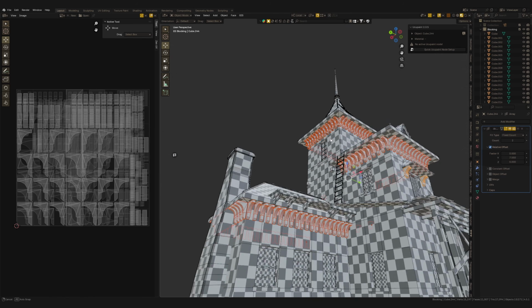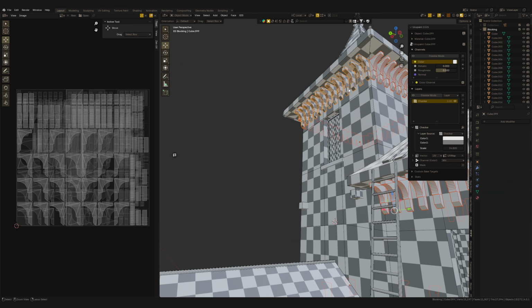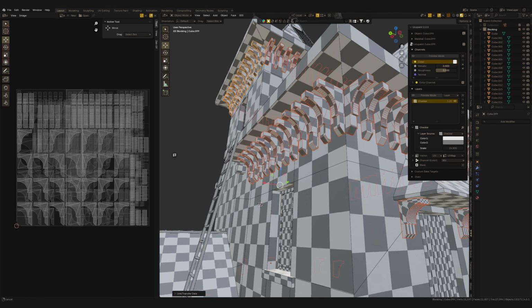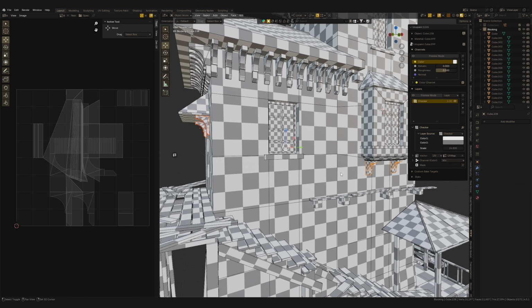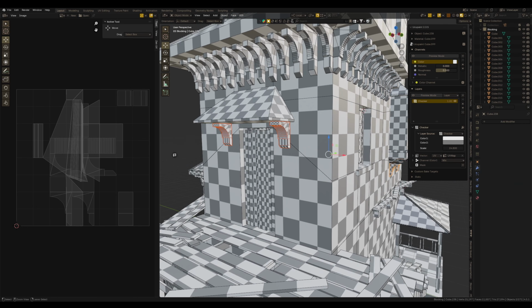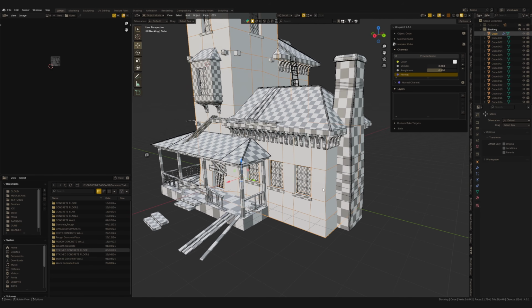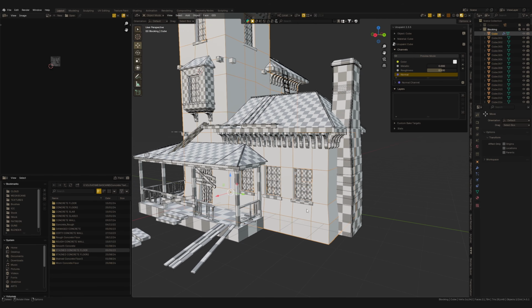For identical objects we can copy UVs using Ctrl-L and copy UV maps, just like we do with link materials. This makes the boring unwrapping process a bit easier. I'm not a huge fan of unwrapping, and I know a few people who like it, but we have to do this if we want texture paint looking correct.